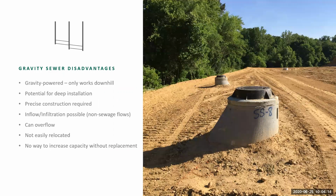Some of the disadvantages of a gravity system, well, it's gravity powered, so it only works downhill. So if your site's got a change or an increase in grade, the sewer's got to maintain the downward slope. So there's a potential for some deep installation. Precise construction is required. Typically, these systems are designed with minimal slopes, and because slope is an important part of the capacity of the system, it's very important that those slopes are met.